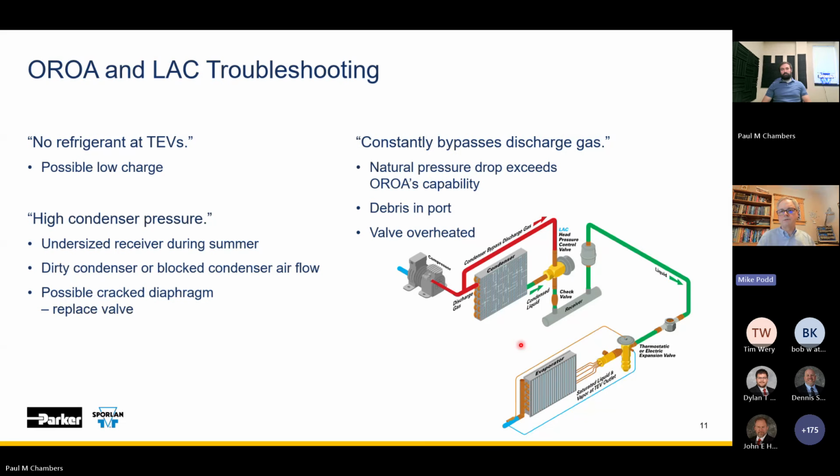So you're not going to see the refrigerant at the TX valves. It's not necessarily that you're going to see bubbles, which you may if it's a bypass problem, but ensuring that you've got sufficient refrigerant charge is key. And it's hard to do because most receivers on small capacity systems do not have a level indicator. So you've got to work off some assumptions there. Sometimes you've got to pull the refrigerant out. As a service tip, you pull refrigerant out until the sight glass starts to bubble. Then you charge to the clear sight glass. So now you've got an operating charge for that day.